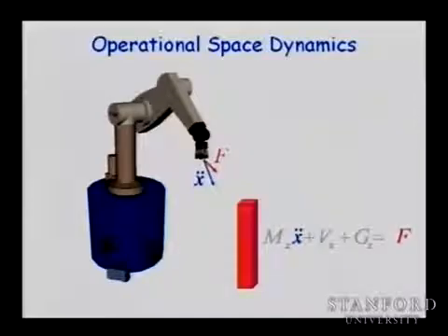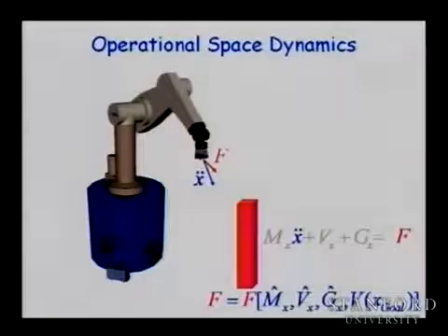You find your f, you multiply it by J transpose and transform it into terms of torques. And suddenly now you are directly controlling your robot in operational space, in the space of the task. And that would allow you to control directly your errors in that space. So your force control will be a function of those estimates, in the same way, with the same structure that we saw just earlier. Okay?